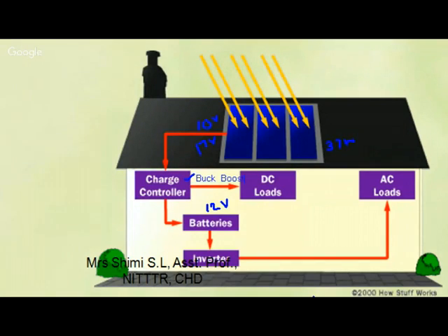When you require a boost, I didn't ask about buck boost or buck. I'm asking when will you surely go for a boost converter? That depends on the application. When you want to charge a battery, you go for a buck converter. When the radiation is very less and you still want to charge your battery, and when the radiation is more, that time also you go for a buck boost converter. I'm asking when will you go for only a boost converter? Any idea?